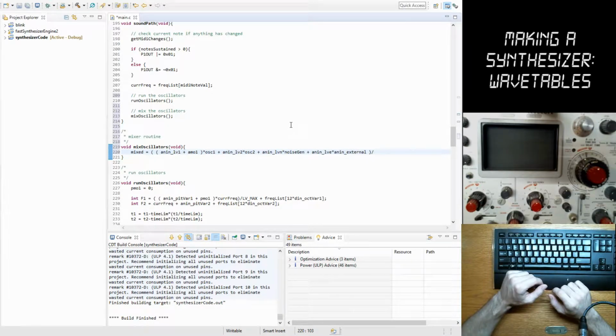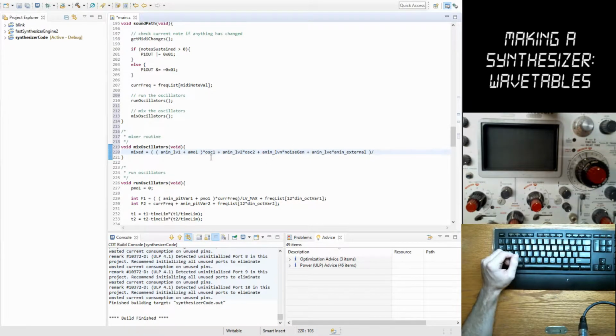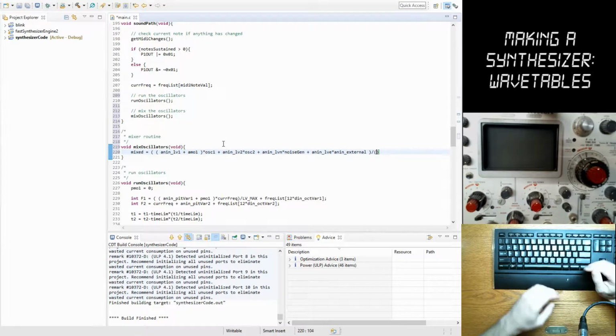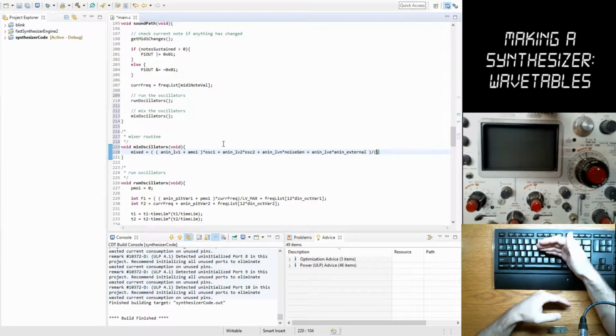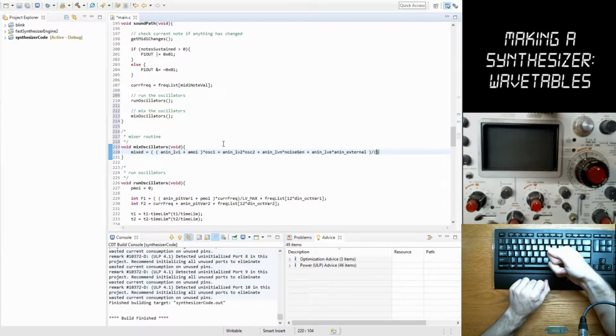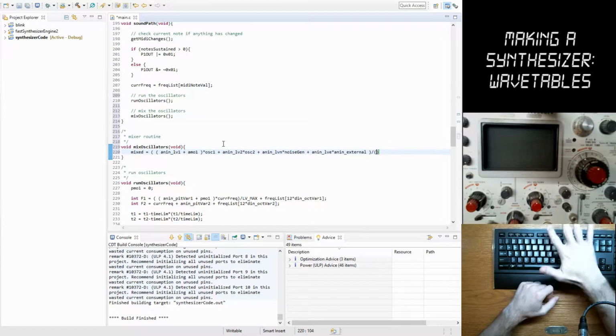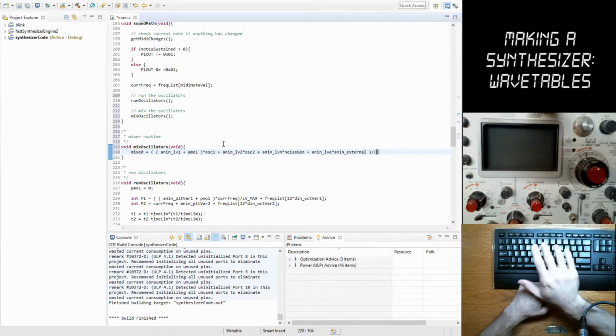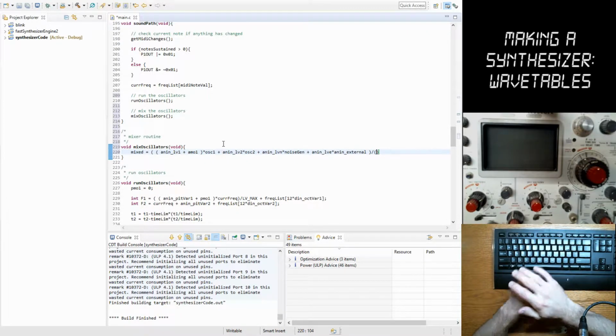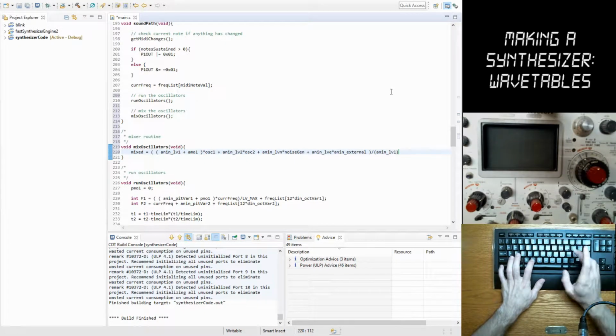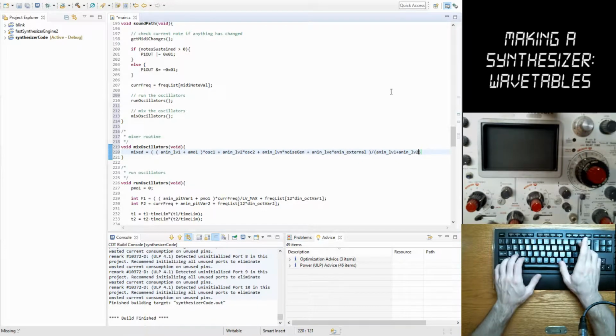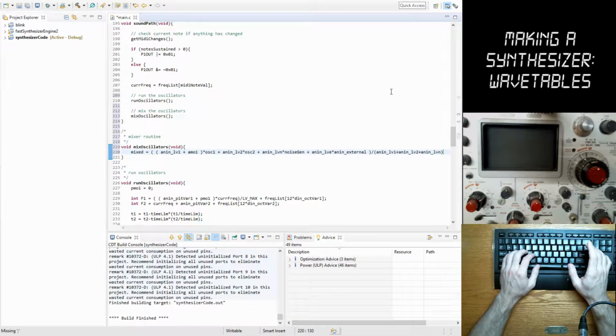All right, and because we're doing integer multiplication, we also have to scale this thing. If you're doing a true mixer, you would just divide by 4 and go forth with that. But in this case, I'm actually going to scale it by how much I'm multiplying things by. And that way we always have a full height waveform and full resolution no matter what we do. The only issue with that is as you adjust the mixer while a sound is playing, the amplitude could dip a little bit, but I don't think it'll be too much of an issue in this case. So 1, 2, noise.